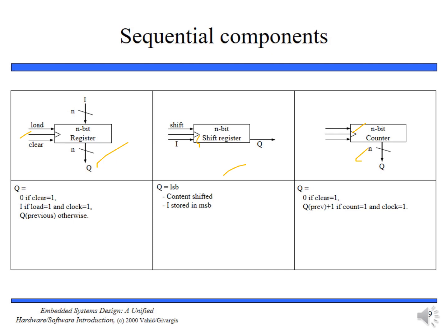Another type of flip-flop is the SR flip-flop, which has three inputs: S, R and clock. When clock is 0, the previously stored bit is maintained and appears at Q. When clock is 1, the inputs S and R are examined, otherwise the output will remain as it was before.